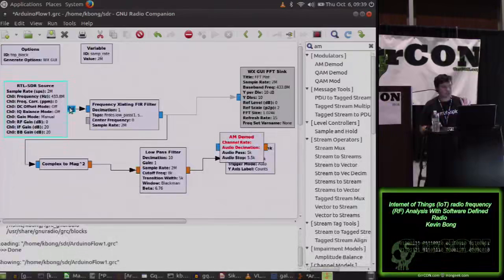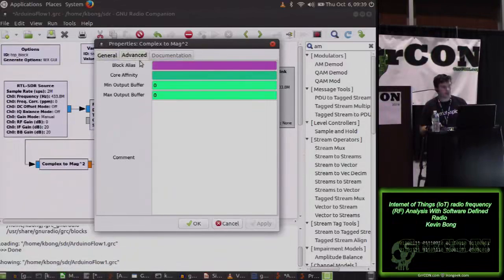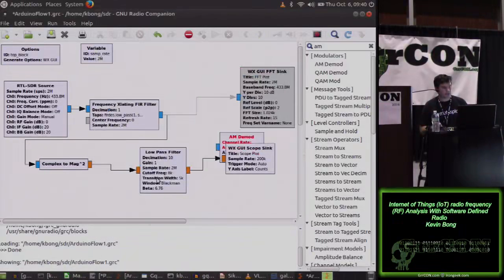One of the other interesting gotchas, you see these different colors. You join the blocks by clicking on this one and then clicking on this one, it creates an arrow. But it'll only do that if they're of the same data type. So these blue blocks are of a complex data type. These orange blocks are of a different data type. And that's something we can actually set on some of the blocks, like what type of output it's going to give. But you can only join them together if they have the right data type. And if they don't, you're going to get little red errors. Like I got an error here because I've added something that's not joined, and you can see it's got two different input and output data types.